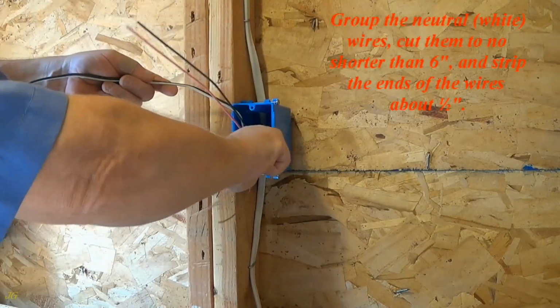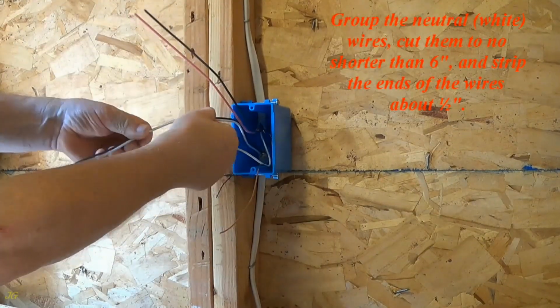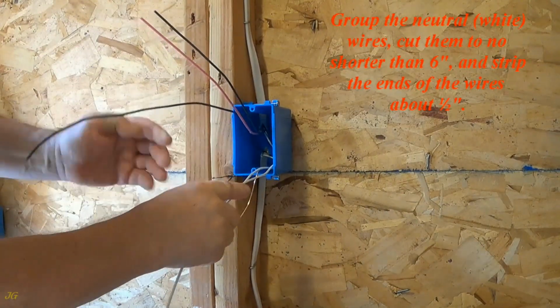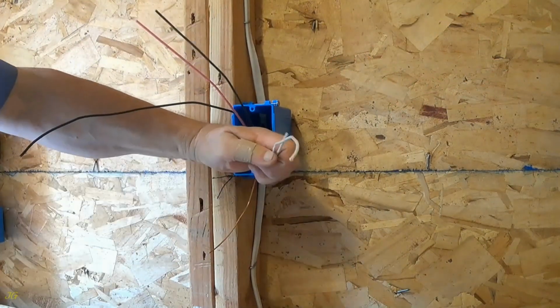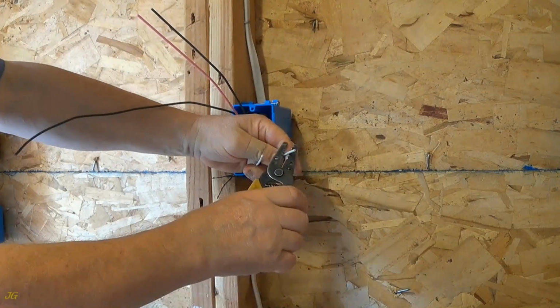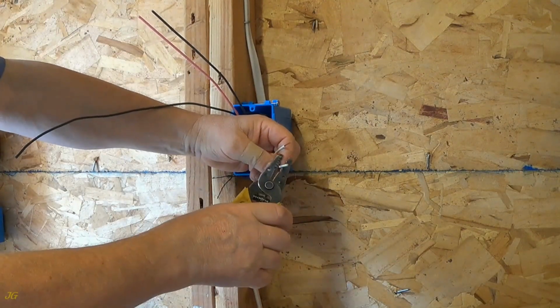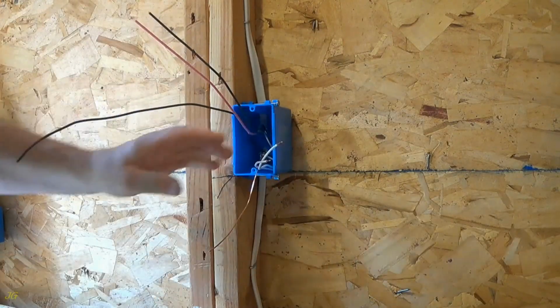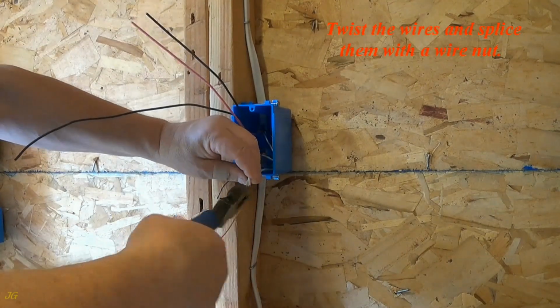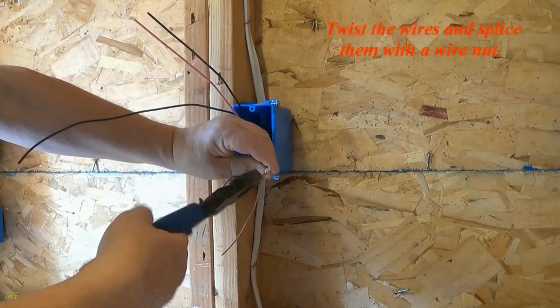Group the neutral, white, wires, cut them to no shorter than 6 inches, and strip the ends of the wires about 1/2 inch. Twist the wires and splice them with a wire nut.